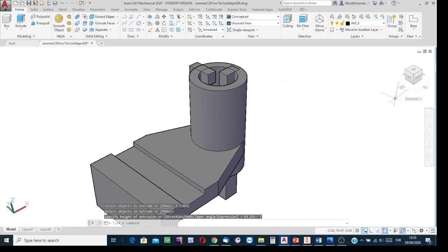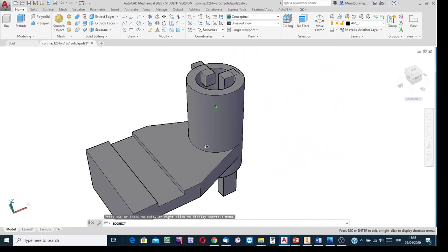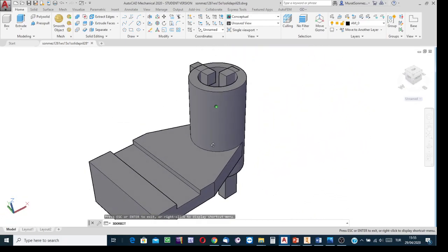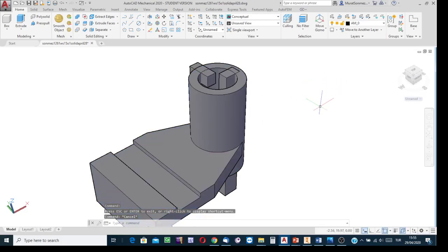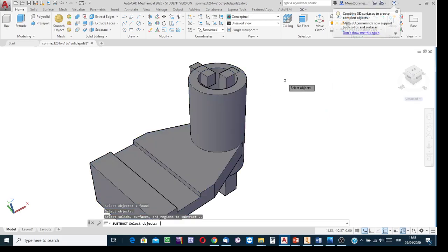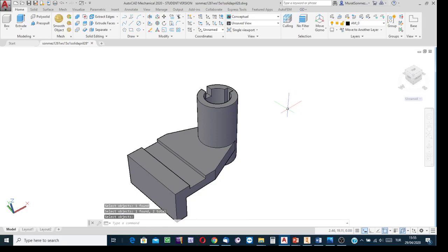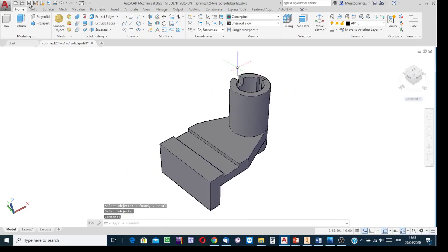Press enter. And then what I have is two solid rectangles. These are to cut the material. Subtraction process. Okay, start, indicate the main part, press enter, and then indicate this rectangle to subtract, indicate that rectangle to subtract. Press enter. Yes, managed to create the channels.